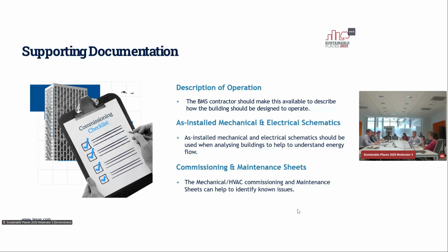Any available manuals on operations and maintenance help that understanding. If available, as installed or as built schemes for mechanical and electrical systems are very useful in our experience to help understand the energy flow. And that as built is key, because usually the design doesn't reflect what has actually happened in the building. So it's important to start off on the right foot.